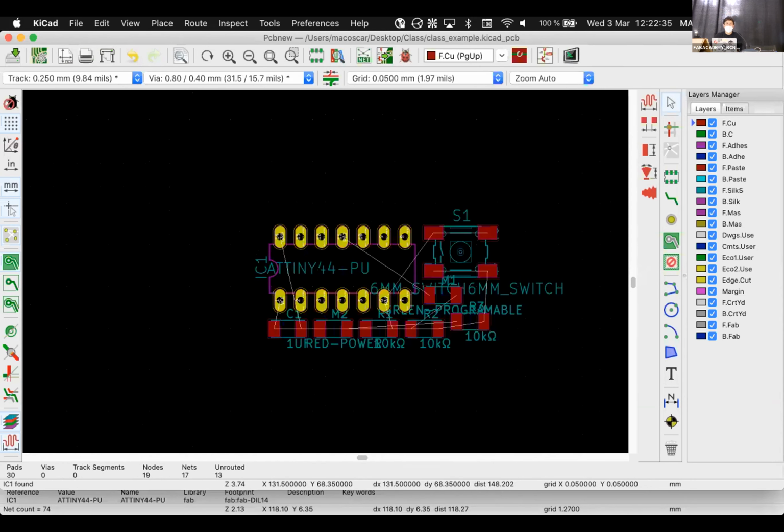Okay, so now I'm here. So you see that this is basically how KiCad put the components, but there's no actual physical board here. Here we have to start arranging them, and here becomes the fun, let's say. This is where the first days you're gonna have a lot of struggle routing. You have to put the components and make the wiring connections so that they match and that you are able to fabricate them. And this is where the craft and the skill comes into place, okay? Experience as well, with time you will get less frustrated. At the beginning, I'm sorry, you have to be a little patient.